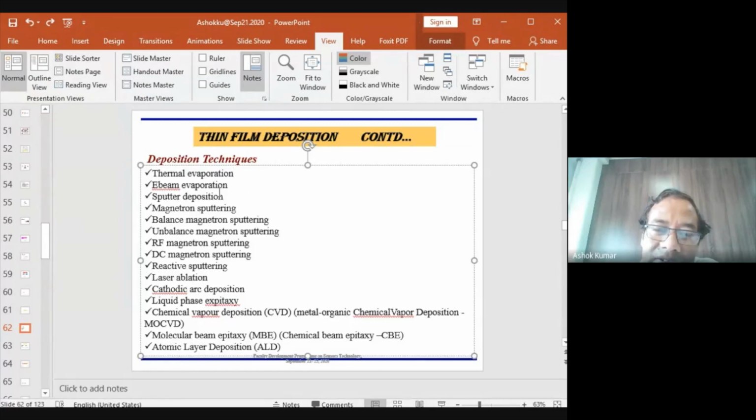The same thing is happening here. Thermal evaporation, or E-beam evaporation, gives you this ordered film, and sputtering normally gives you amorphous film, but you can still make it crystalline by post-processing. How? Post-processing means heating. Why? By heating, atoms can move to other places. Because heating means kT, where k is the Boltzmann constant and T is the absolute temperature. If you are heating something, you are giving kT kind of energy. That energy can move the atoms and they can settle into the proper sites.